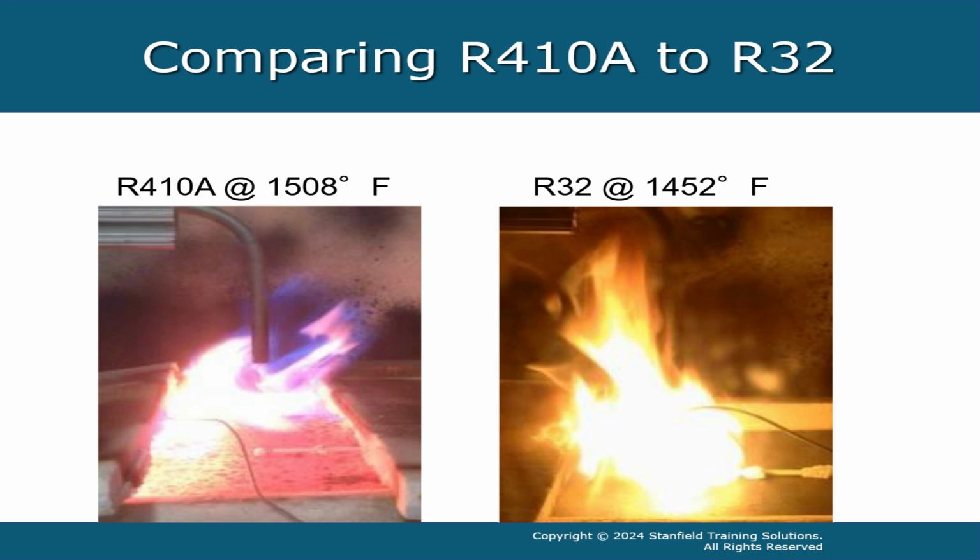Here are 2 pictures from a paper entitled Auto Ignition of R32 and 410A Refrigerant Mixtures with Lubricating Oil. They tested the ignition of refrigerant alone and then the refrigerant with mixtures of POE. The picture on the left is a picture of 410A igniting when blown directly onto a hot plate of 1508 degrees Fahrenheit. The picture on the right is a picture of R32 igniting when being blown directly onto a hot plate of 1452 degrees Fahrenheit.